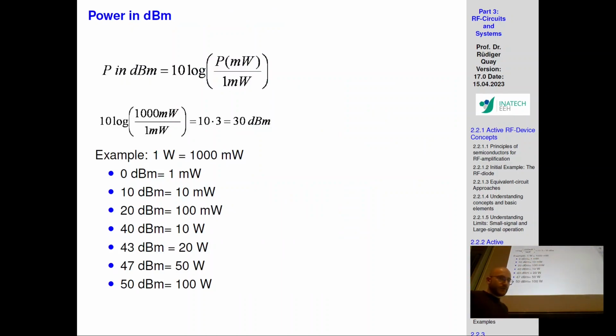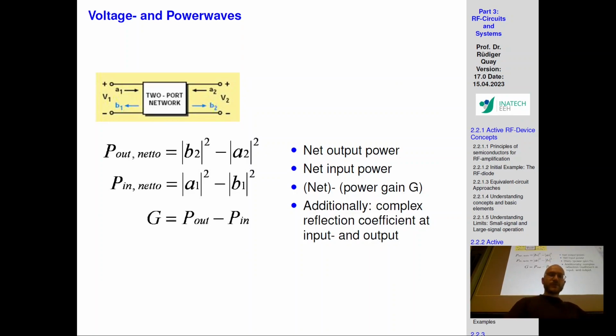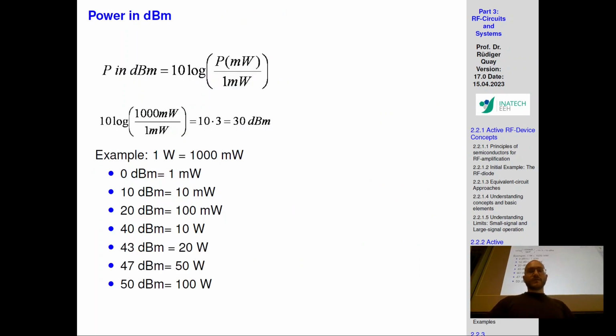Power, in this case, why we were able to say the gain was P out minus P in, the gain was divided in dB. We're taking these milliwatts and we're transferring them into dB scale. And I think probably you've been familiarized with this, how that works in the 10 log 10 scale. 10 log base 10 of your X, which is your milliwatts for your power.